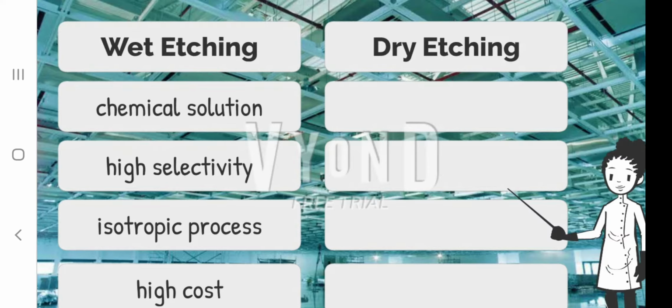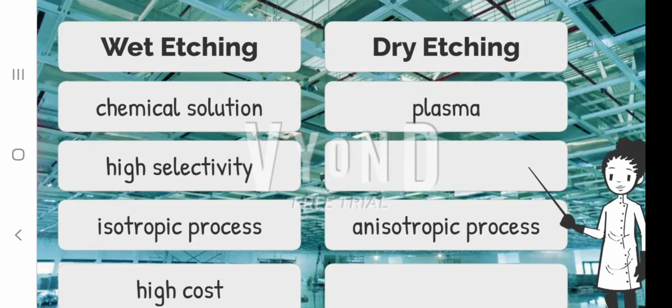Dry etching uses plasma or high energy ions to remove the targeted material, and it is an anisotropic reaction where the process only occurs exclusively in one direction and the process is easier to control. This is significant as we do not want to remove materials under the photomask, and the critical dimension loss will be almost 0 to none. This process also costs less as its byproduct is in gas form, thus lower handling and disposing cost. However, dry etching has a relatively low selectivity.